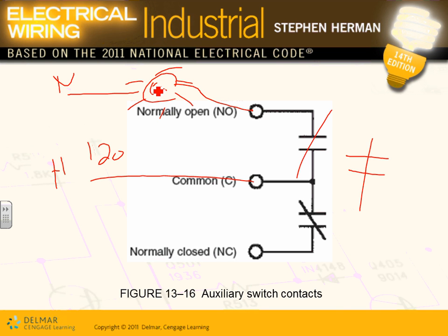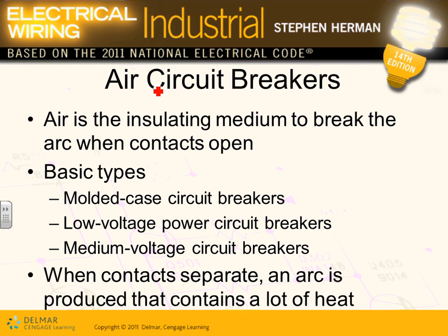Any comments, gentlemen, about auxiliary contacts or switches and shunt trip? Very, very important. This big boy, Adam, has tons of auxiliary contacts and shunt trips that you can remotely trip. You can push your iPhone and turn this on and off from your iPhone. That's through the auxiliary contacts and so forth. So big deal with bigger breakers.